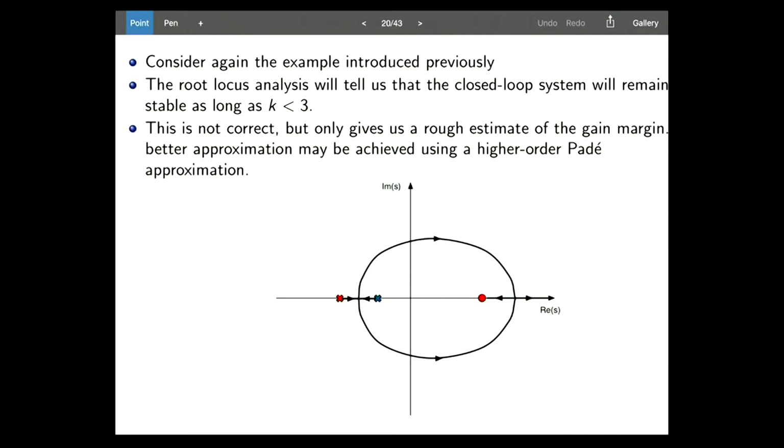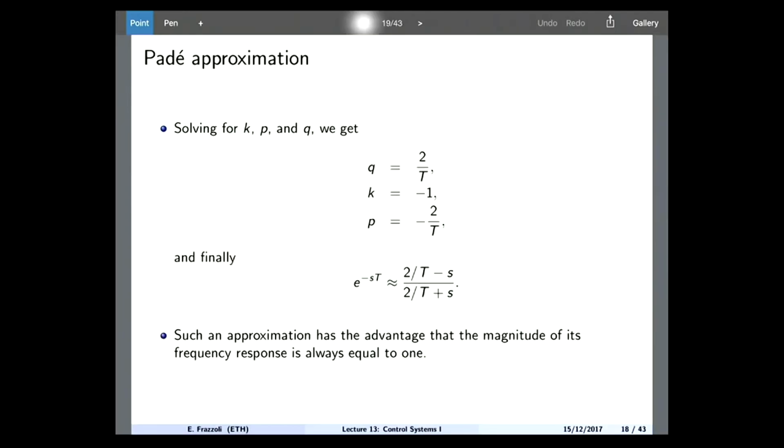Is this what I said? And how do you resolve the fact that this is not what I'm showing here? Right, so what I said is that the positive k root locus is on the left of an odd number of poles and zeros. This is the reason why I always say, if you want to do root locus, write your transfer function in the root locus form.